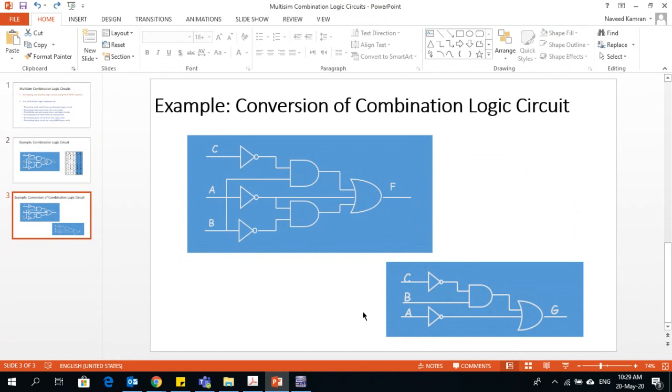It will also have a faster response because remember, each gate takes some time to change its state. Although that time is in nanoseconds, imagine a very complex combinational logic circuit in which hundreds or thousands of gates are involved. All those nanoseconds accumulated together will end up as a delay.